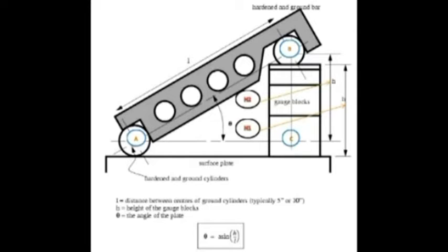Generally it's a precision instrument to measure angles very accurately and to locate the workpiece to a given angle within close limits. It consists of a steel bar and two rollers. The sine bar is made of high carbon, high chromium corrosion resistant steel, suitably hardened, precision ground and stabilized. The rollers are of accurate and equal diameters. They are attached to the bar at each end. The axes of these rollers are parallel to each other and also to the upper surface of the bar. The normal distance between the axes of the rollers is exactly 100 mm, 200 mm or 300 mm.